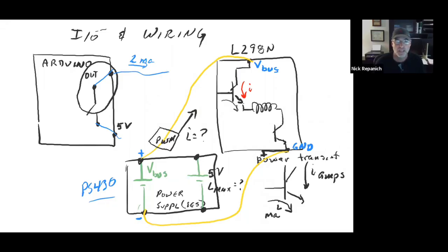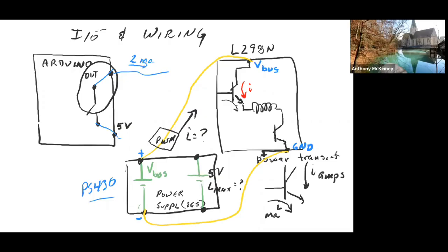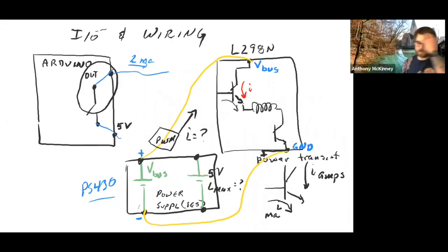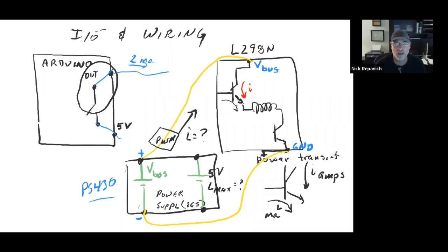And that big, huge capacitor, what's the voltage of it? 10,000 microfarads, 50. Looks like 50 volts. There you go. WV, yeah, 50 volts. Okay, so good. And that part of the power supply, what's it rated at?